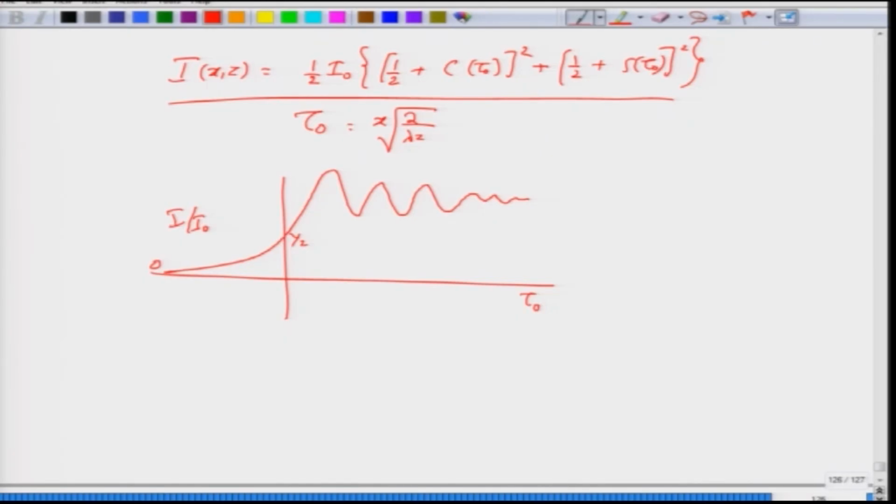What it means is that at some point the field is reinforcing, at some point the field is actually not reinforcing. Please recall our breakpoint analysis that we did. There was a minus 30 dB per decade or 20 dB per decade, and then there was a minus 40 dB per decade as the long range attenuation. However, around that we saw that there was a shadowing effect, and this is exactly the shadowing effect.